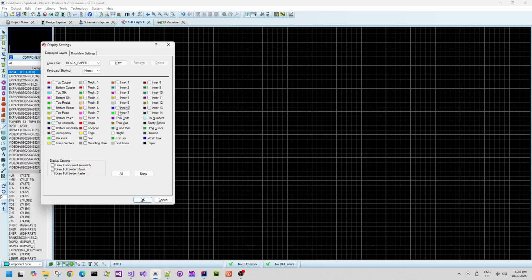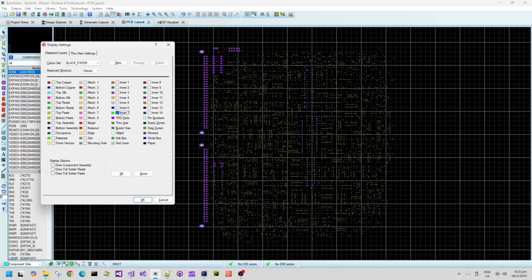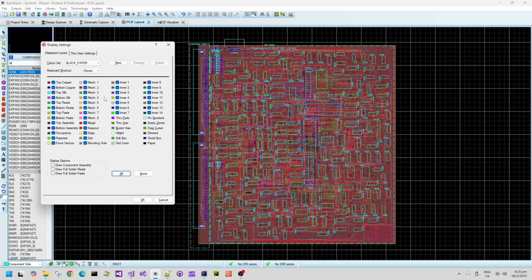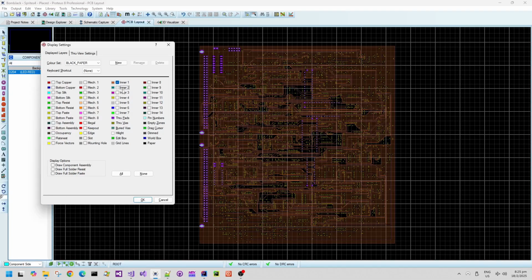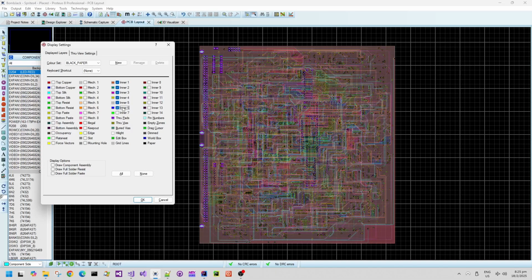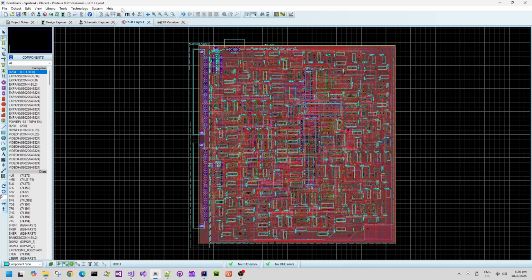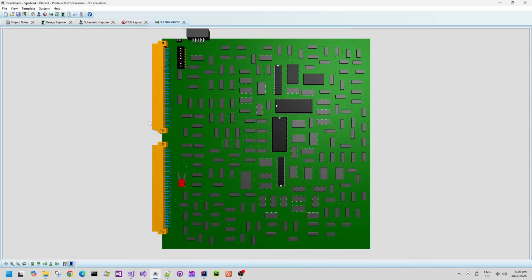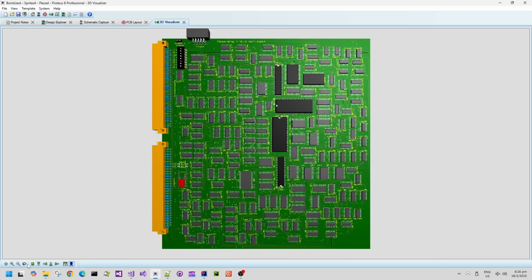There's still going to be some signal integrity issues from these partial power planes. Some of them are tied to ground, some of them are tied to positive voltage. So we can see here that when I turn on all of the inner power planes, you could see that most of the PCB copper area was covered.